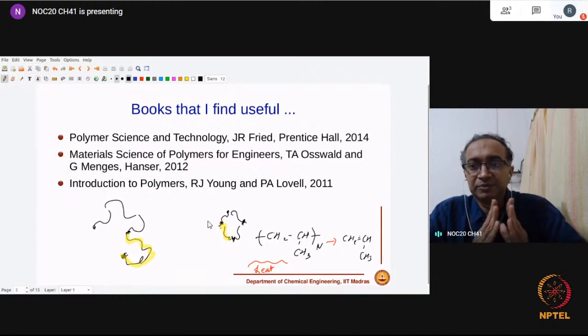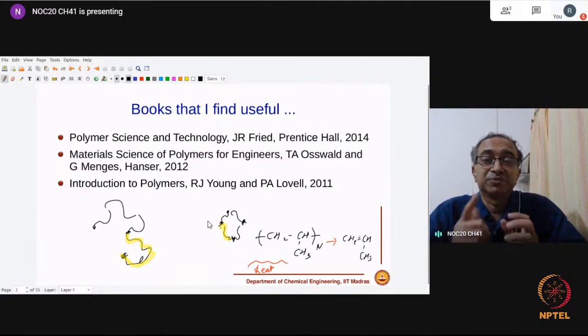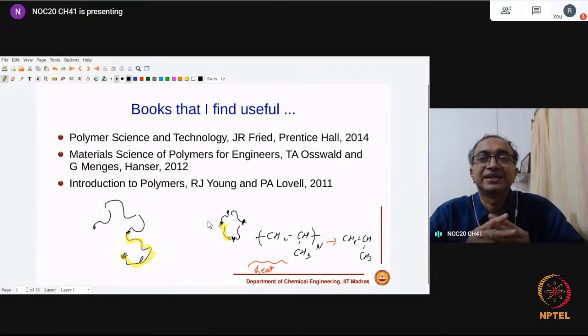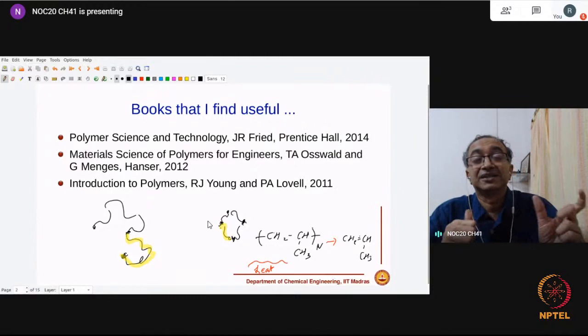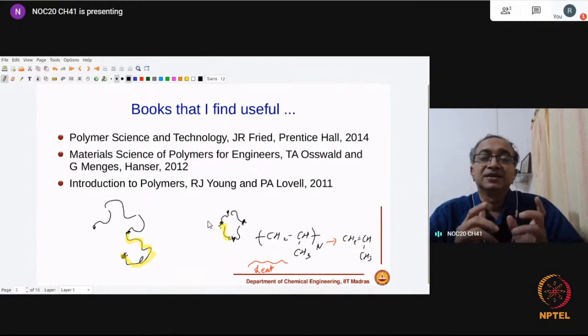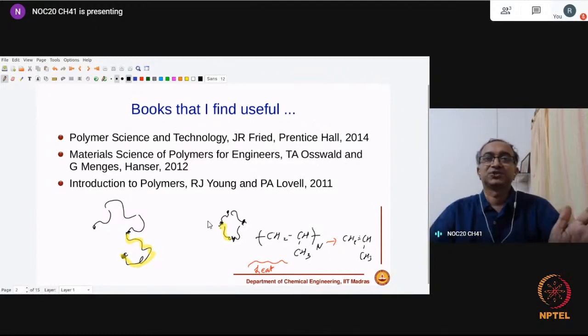Yeah, so Durga Bhavan is asking, for example, polyethylene is cross-linked, and yes, if you de-cross-link it, then you can get polyethylene. But as I mentioned, during the process of de-cross-linking, you may end up reducing the molar mass quite a lot, because there are some other places where the chain will break. Other issue is you might induce oxygenated groups in the polymer. See, polyethylene works very well in given applications because it's just a hydrocarbon, CH2, CH2, CH2, CH2.